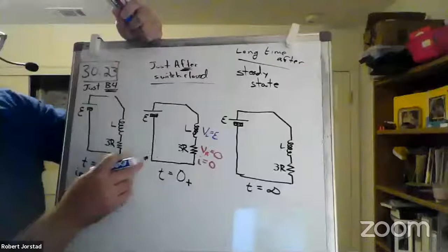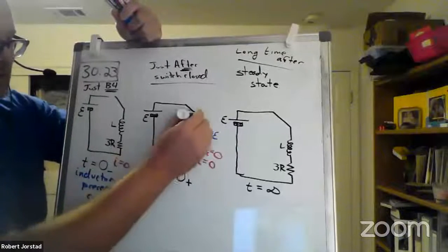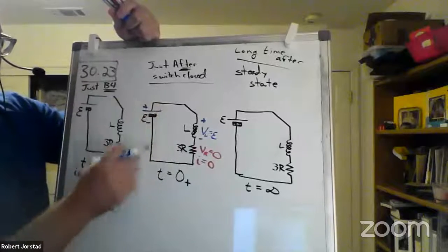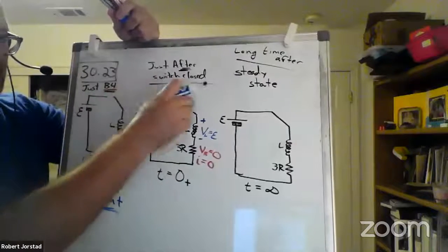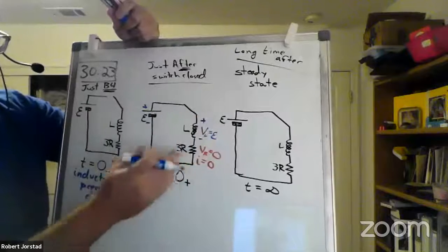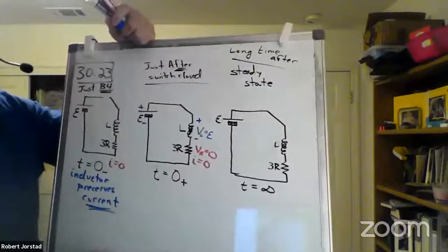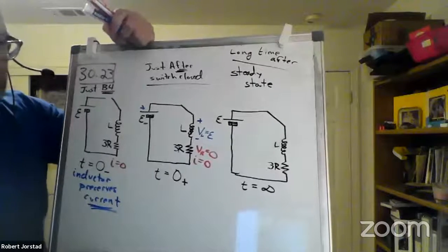All the voltage is across the inductor. What is that? Yeah. Voltage equals E. So clearly, if we're going to do a loop here, think about it. If there's voltage positive E on this side, when I go down, I'd have to get a negative E. So again, this is voltage E opposing the current flow. This makes sense.